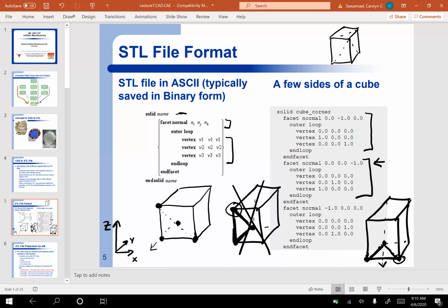So as a process planning software starts to interpret these STL files, what will happen is that the process planning software will understand, okay, as I'm scanning, looking across this part bed, I see, okay, here I've intersected with a triangle. Now, am I supposed to start or stop laying down material, right?